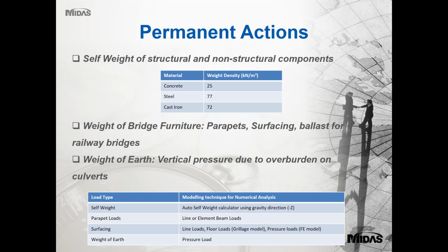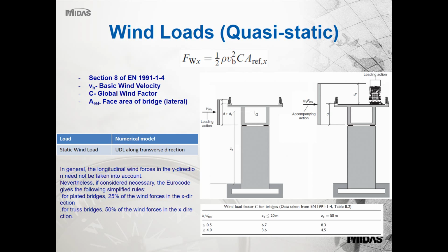Now plane loads are good, but it's always recommended that you actually divide the plate elements and beam elements wherever you have a load, because it makes it easy to extract the results and maybe later on change the value of the loads, or move the nodes a little bit inner or outer to adjust the actual position of the dead load. Okay, now moving on to this next part, which is wind loads.